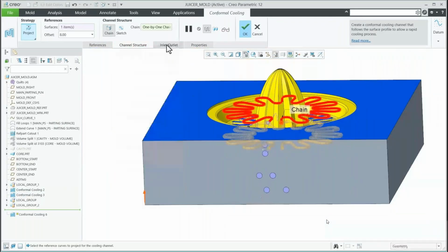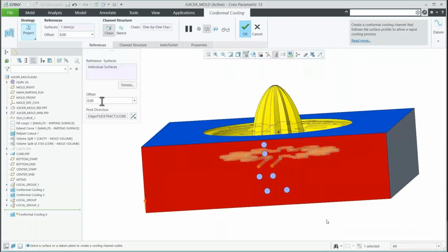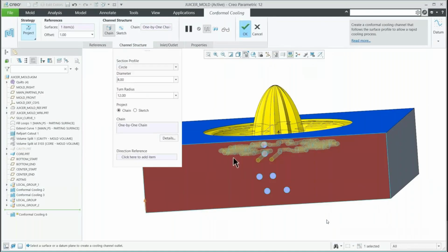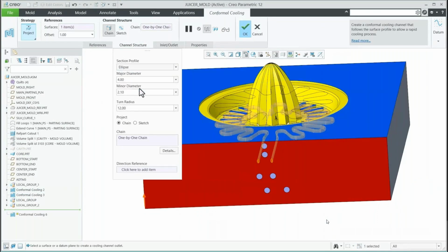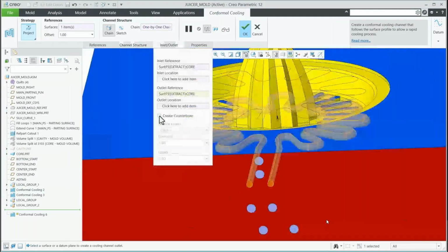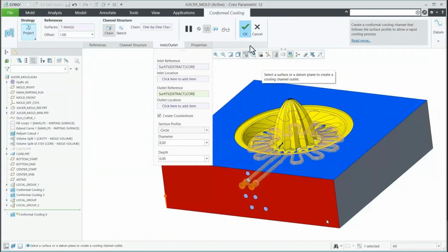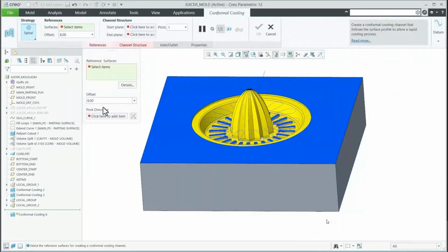Plastic is cheaper to build, and if my product is not correct, okay, I print a new one, the prices are okay. If you do the same in metal, and if it's basic metal, maybe, but if it's an expensive metal or a stainless steel, it gets more and more expensive. You see here now they make that cooling line a teardrop shape, because then I don't have to build support structures in there to make it.